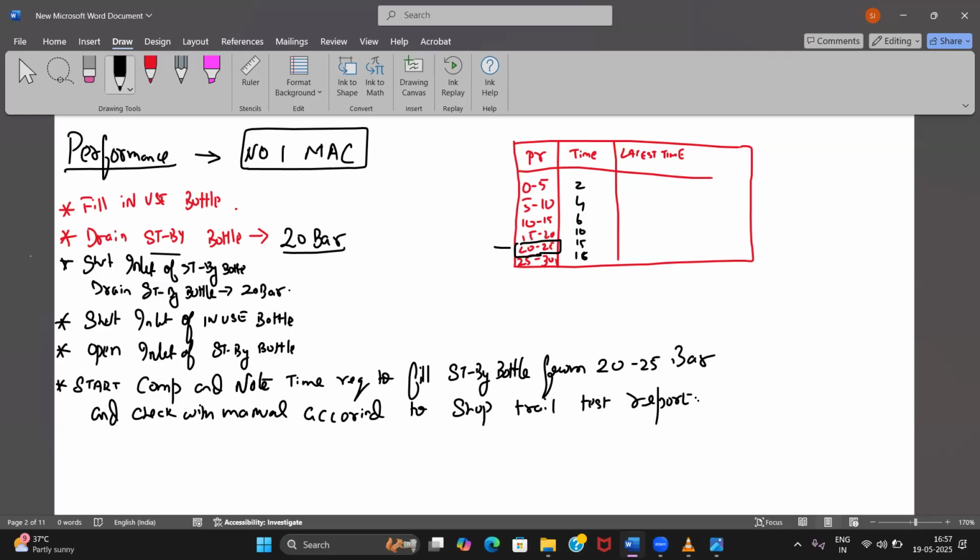Yes sir. So it will give you an indication that suppose here it is 15 minutes, for example, and you are taking around 18 to 19 minutes. What does it indicate? It is taking more time to fill. There could be problems with your piston ring. There could be problems with your valves. Okay, isn't it?